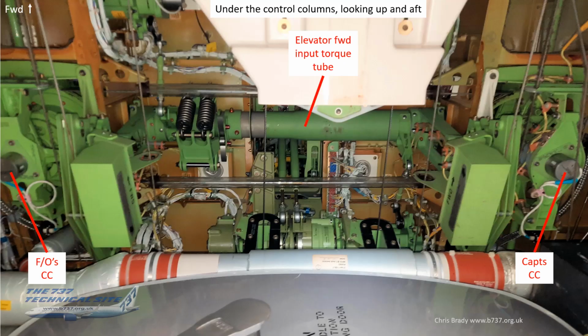On to elevator control. Again, we've got this great little photo, which you may remember from a previous presentation, but I'm going to use it again because it shows everything we need to see here. We are under the control columns, looking up and slightly aft, so forwards is to the top of the picture. On the left and right hand side, those circular, metallic, cylindrical shapes are the bases of the FO's and the captain's control columns. They are interconnected by this elevator forward input torque tube, which you see running across the picture left to right.